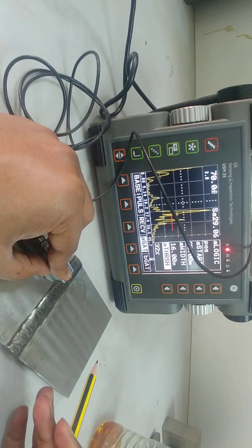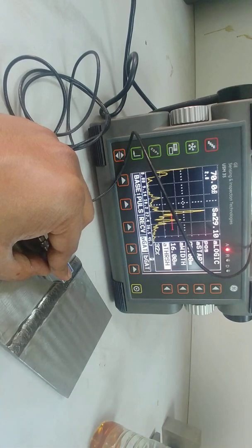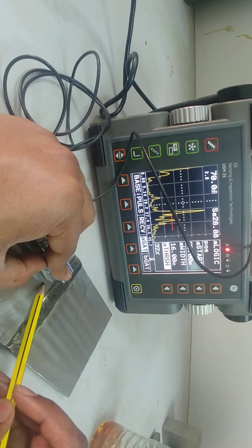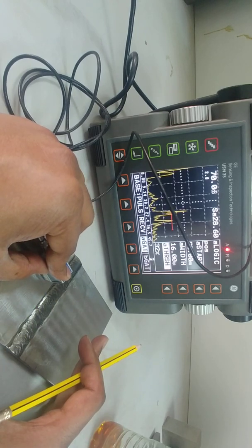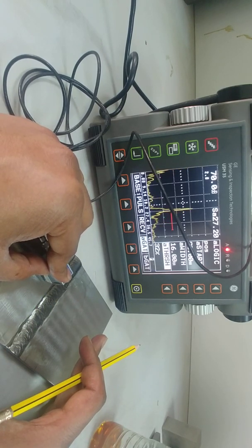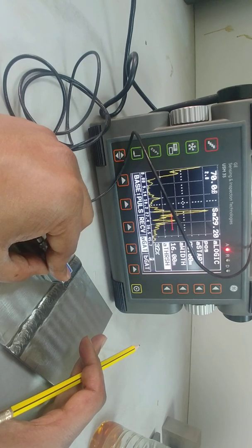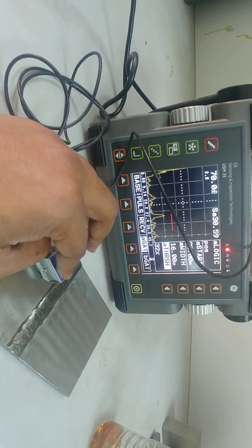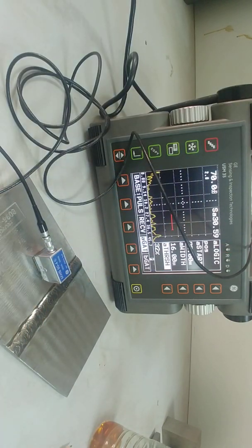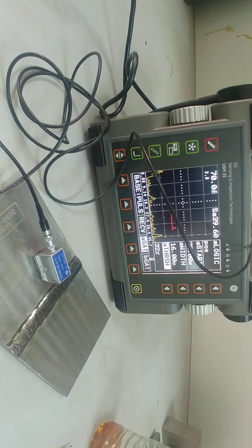Now, how we are measuring this one is, we are measuring from 50% of the signal to 50% of the signal for measuring the length. What is the size of the defect? You can see on the bottom side, I'm trying to measure the size of the defect. So I'm taking it 50, trying to move it, get a bigger value, and move it further away to get 50% of the signal again. So this is how you will be testing, you'll be getting the defect size. Now, I think we can stop here. We can make a report in the lecture class.